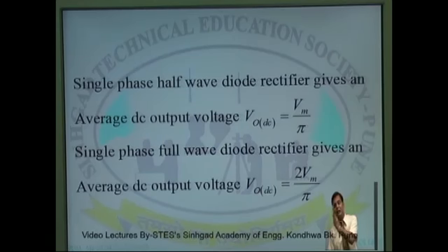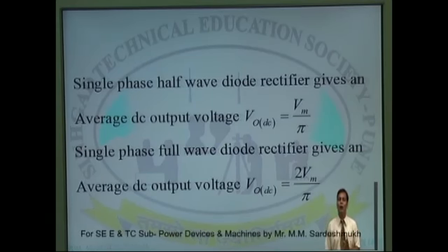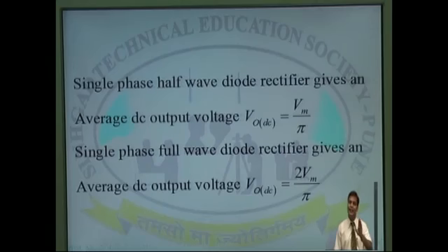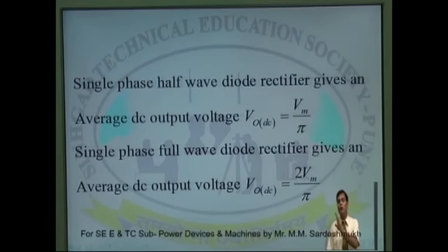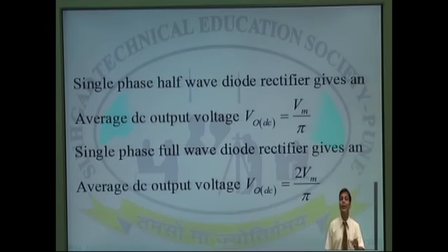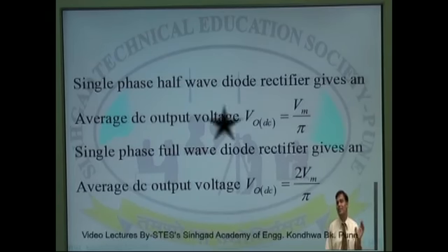We can control the conduction angle of the output voltage, and the conduction angle of the output voltage can be from 0 degrees to 180 degrees. So that is what is possible, and in this way we can control the output voltage in the case of a controlled rectifier.